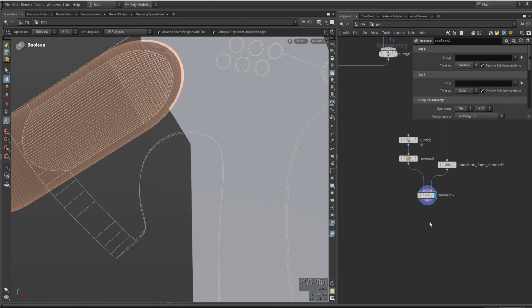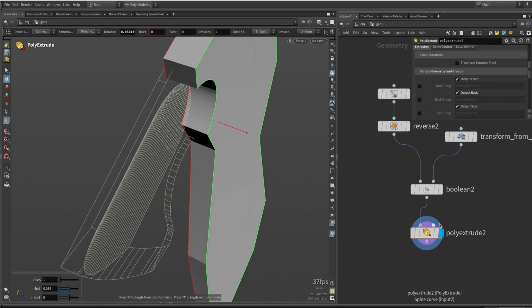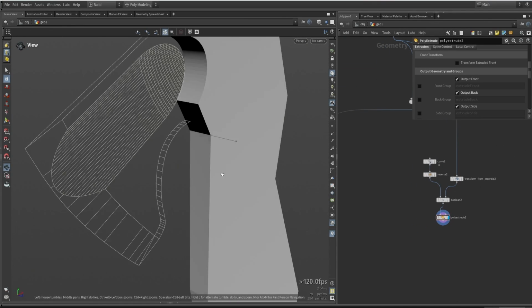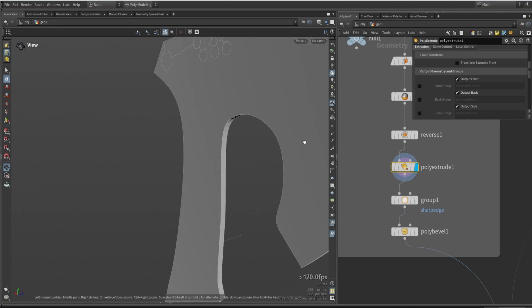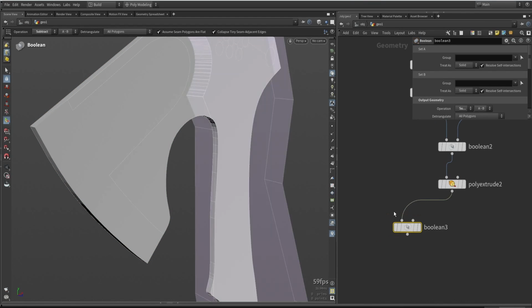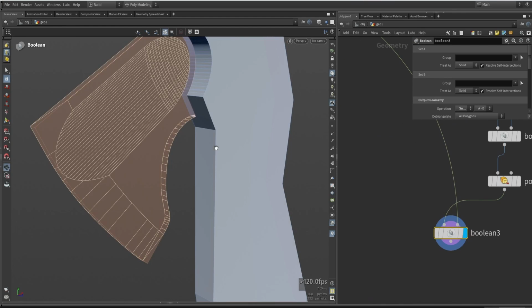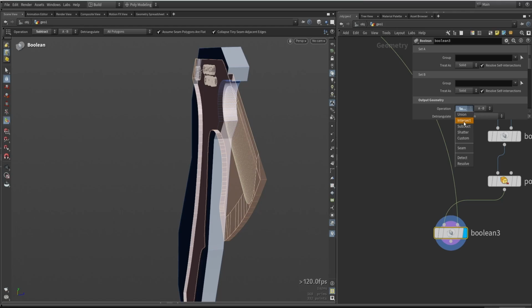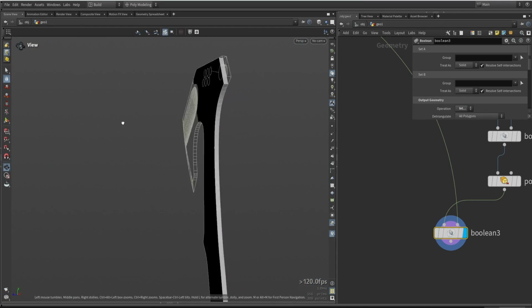Then we also need to do an extrusion. So simply do poly extrude, and let's close it here as well. So now comes the magic where I want to subtract the base shape with this shape. And we will go back here to our extrude that we had before. And we're going to do, again, subtraction of both. So I will subtract my current shape that I'm working on with our base shape that we had from the beginning. If we subtract these now, or we actually need to set this to intersect now, we have a perfect cutout with all the curves and lines that we had before.